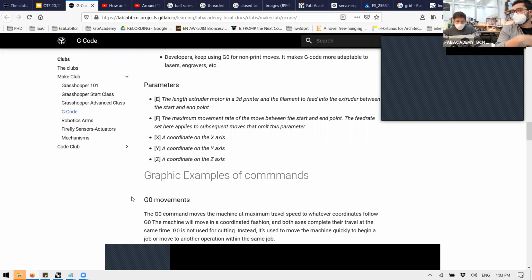So you're able to make a lot of customization, change things on the go, and tweak how the machine works, because you can send a command before another one. For example, you have seen that 3D printers right now hit the bed, then they hit the extruder, and then they print. No? If you know how to use Gcode, in Cura you can configure it to hit the extruder and the bed at the same time. So actually you save 3 minutes.